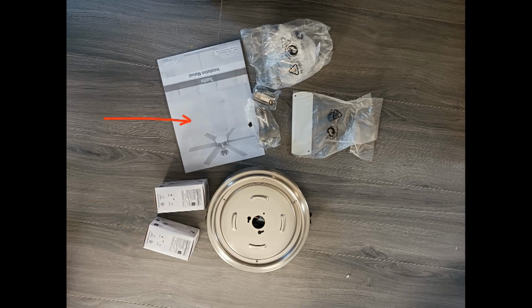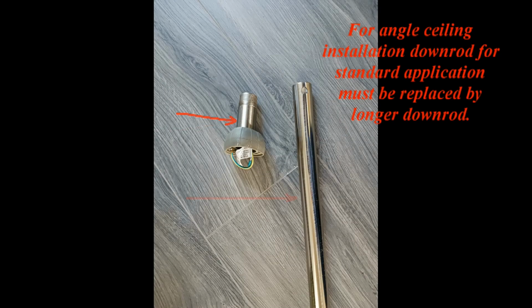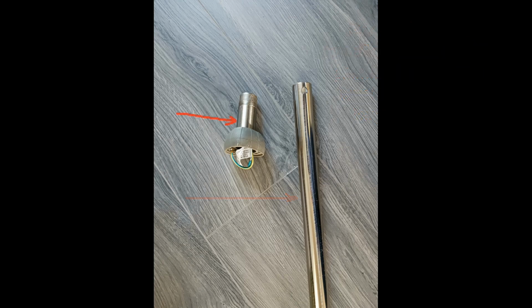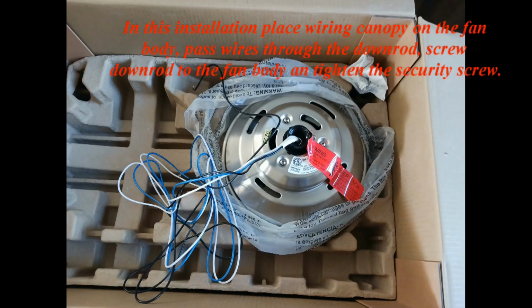Instruction. For angle ceiling installation, the downrod for standard application must be replaced by a longer downrod. Downrod for standard installation: for installation using the standard fan downrod, omit steps for hardware transfer from the standard downrod to any other. In this installation, place the wiring canopy on the fan body. Pass wires through the downrod. Screw the downrod to the fan body and tighten the security screw.